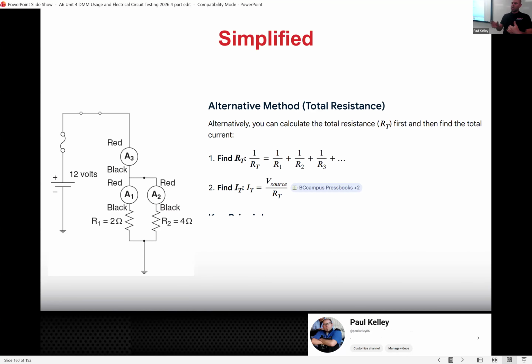So for me, I kind of oversaw it, and I talked with the foreman, and the foreman actually ended up being a former student. I was like, hey, talk to me over here real quietly, because I'm not trying to put the tech on blast, but dude, you see these numbers? This needs an engine because it's got 120 PSI in cylinder 4 on what sounds to be like a dead battery. I'm not even sure that would cause a misfire, you know? So we had a little private conversation.